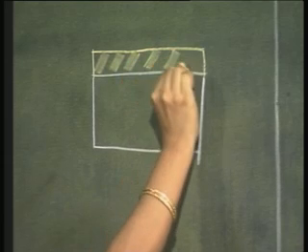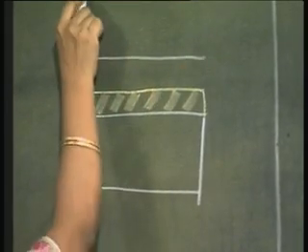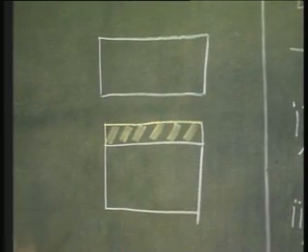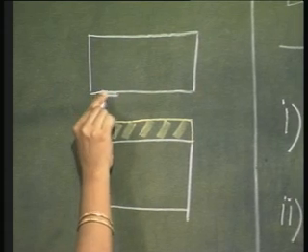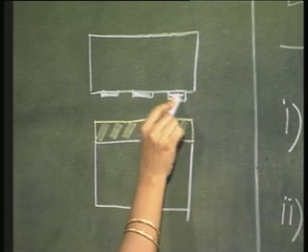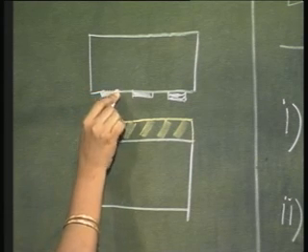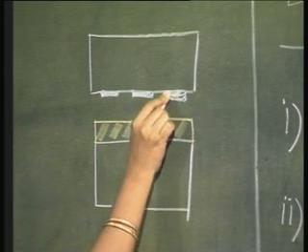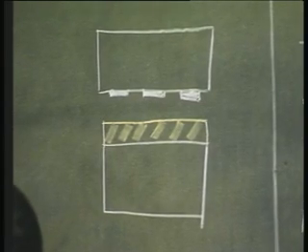I have a layer of photoresist on top of the silicon wafer, and now I have a mask with the proper geometric pattern on that. What do I mean by this? Some parts of the mask are opaque and some parts are transparent. These are the portions which are opaque to the radiation. A mask plate is nothing but a glass plate with these transparent and opaque regions delineated in it.